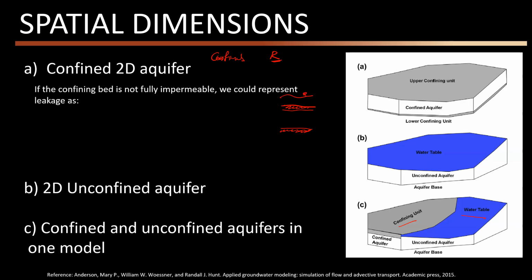So technically, we already solved this example problem as one of our homework. If I know the head here, which is nothing but the depth of the shallow aquifer, and if I know the head here, I can write Darcy's law for this part and calculate how much water is getting from the shallow aquifer into the aquifer, or the other way. Okay, so we solved this problem.